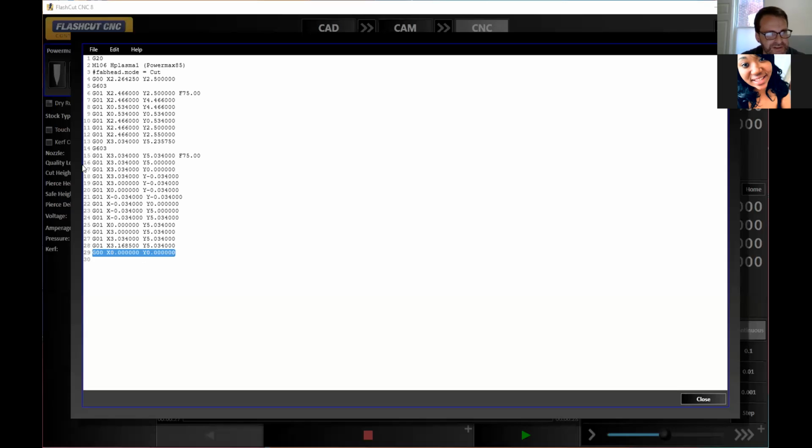All right, now we're going to actually put this in. So we'll go to our Flash Cut. We have basically the same thing, and I'll walk you through what we have to do. After line 3, we have to put in our point of origin command. It's always X0, Y0.